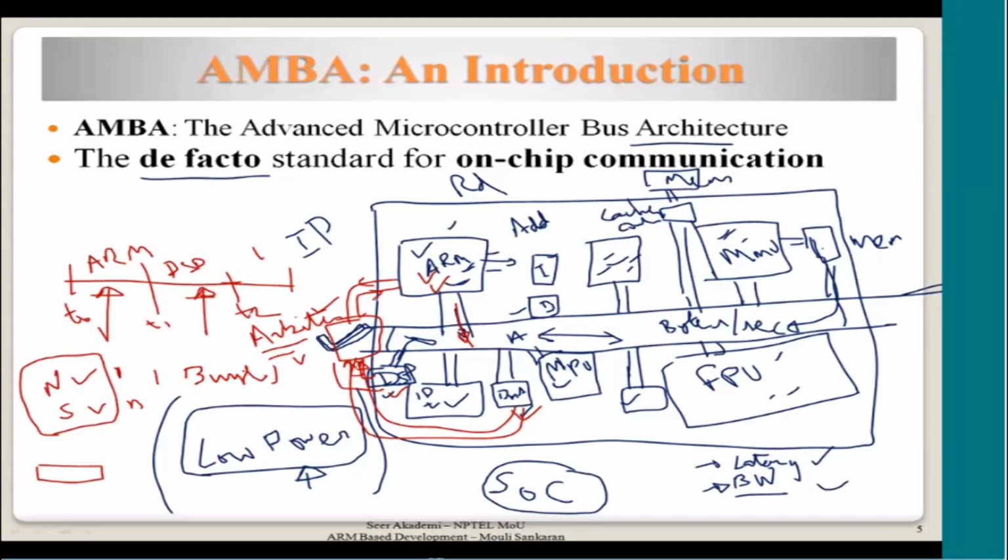That means the initiator gives one address, the first address, then the subsequent accesses are all to addresses relative to this. If the bus data width is maybe 4 bytes, then every address plus 4 will be transacted. That means multiple words over the bus starting from some address. That is called a burst transfer.